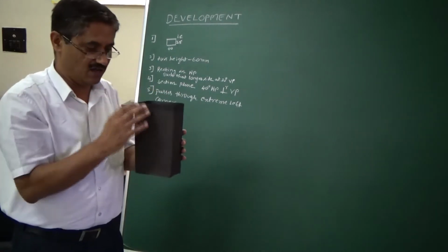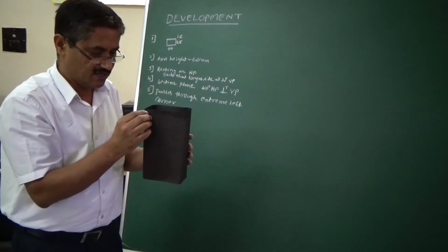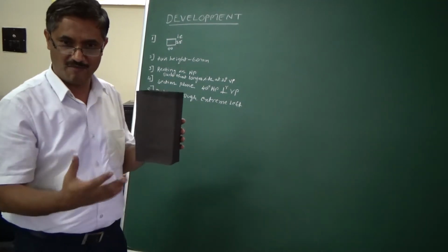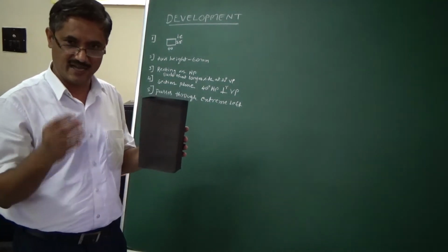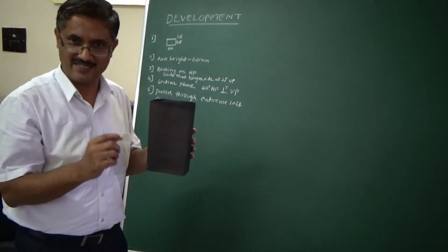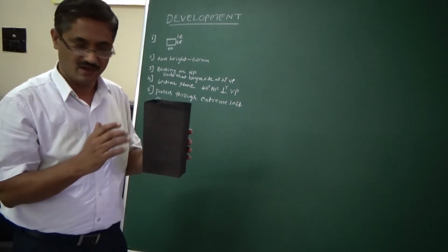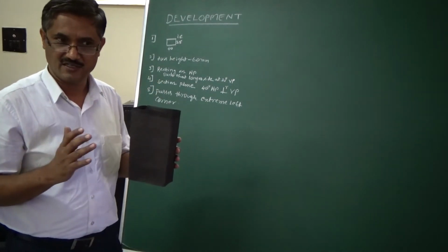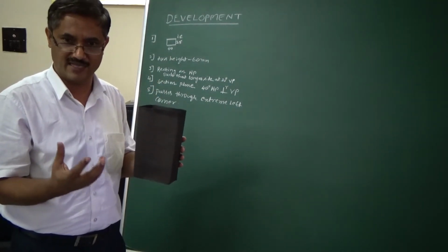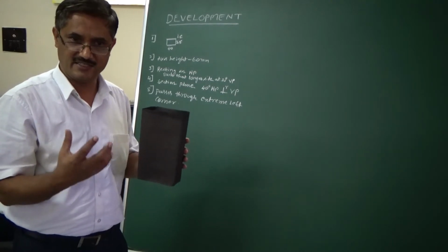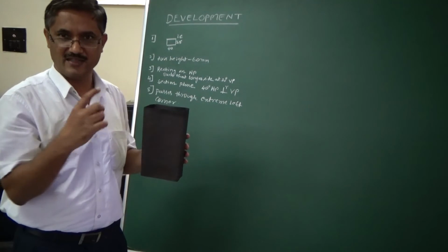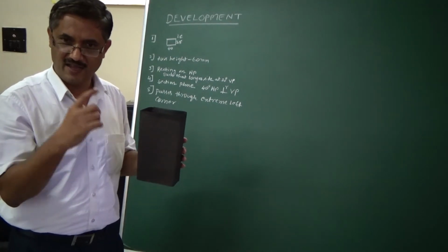When it is hollow inside, we get this surface as sheet material. Normally, sheet materials like MS plates are used in industries to make different objects using this methodology. I can give you a wonderful example of a funnel. A funnel is made of 2 pieces: one is a section of a cone and the other is a section of a cylinder.